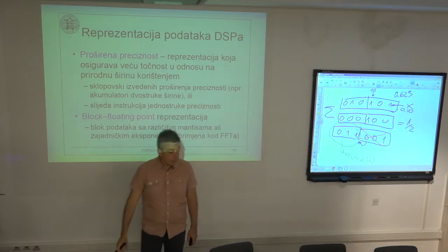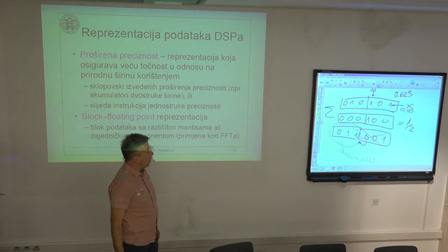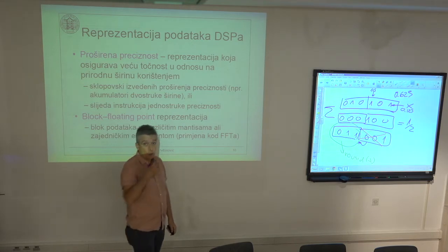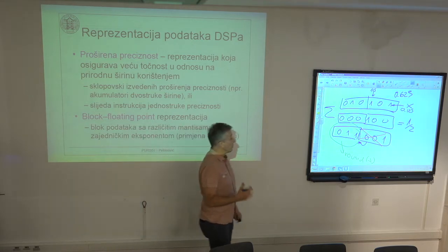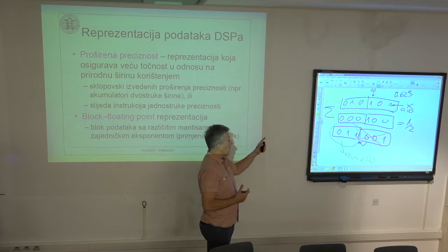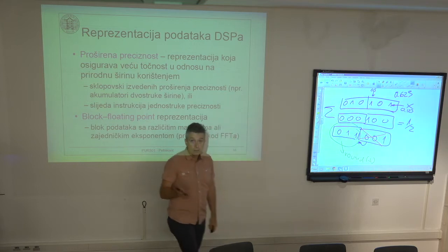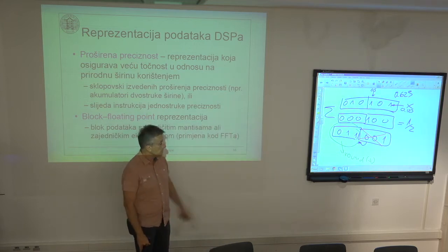So this third bit is 1/8, the first bit is 1/2, and together the value is 0.625. Since this fractional part is greater than or equal to 1/2, I do the round up, and this value of 2 is then increased to 3. Okay, so this is the rounding.